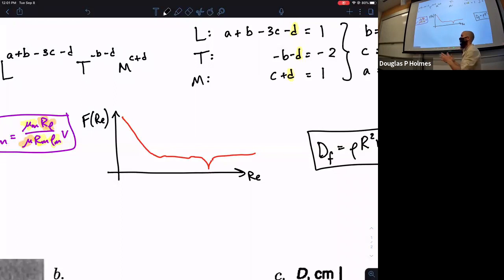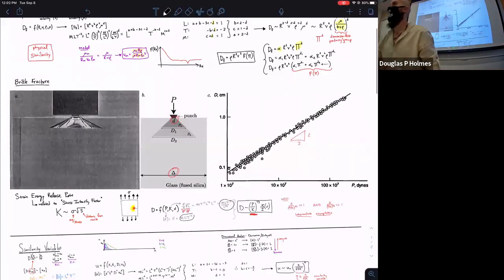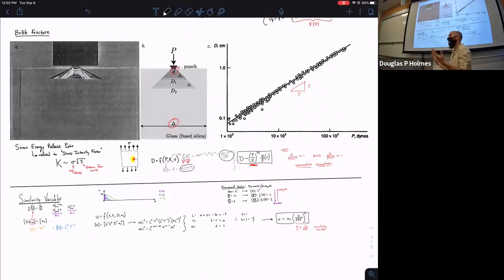Sometimes what you can do is figure out what that functional relationship is in certain regimes. In fluid mechanics, you'll often specify whether you're in the viscous regime, the inviscid regime, or the high turbulence regime, and isolate the function you're looking at and say, okay, in this regime it's constant, or in this regime it's linearly dependent. In this particular problem with concentration, we can solve it analytically. Oftentimes you can combine the tools we've talked about so far: look in some intermediate regime, see how it behaves, maybe look in a different regime, and then try to stitch them together.